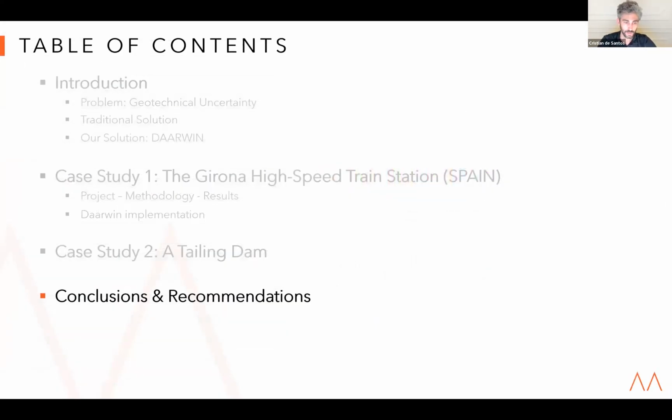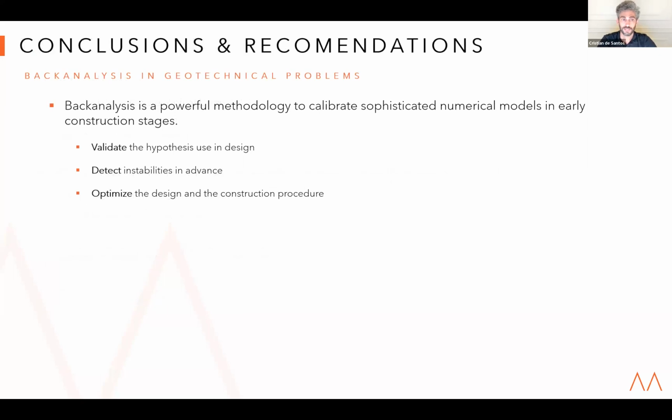Just to conclude, some ideas or recommendations regarding geotechnical back analysis. The first one is back analysis is really a powerful methodology to calibrate numerical models in early construction stages with the idea of validating the hypothesis used in design, detect instabilities in advance, and finally, it's opening us the possibility to optimize the design and the construction procedure even during construction.